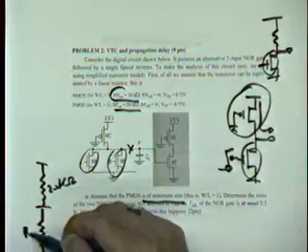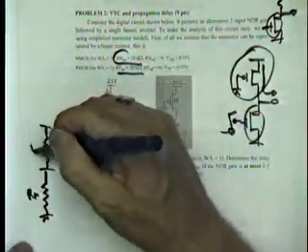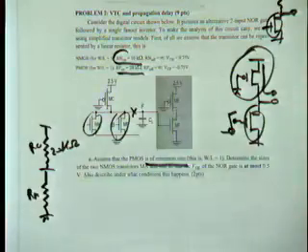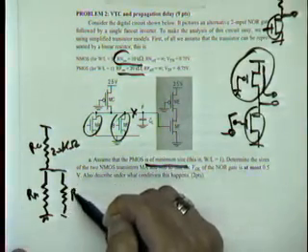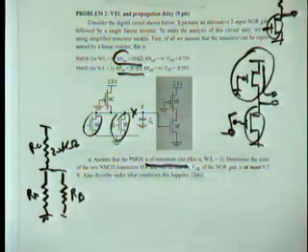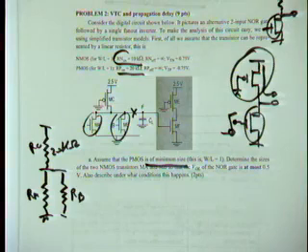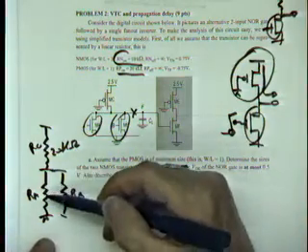Let's call this RA. And this is RC. Okay? If I turn both A and B on simultaneously, what I'm going to get is this. You have two resistors in parallel. Now, which case do you think is going to produce the highest output voltage? What's happening when I put two resistors in parallel? What happens with the overall resistance? It goes down, right? That's right. The first case is the worst case condition.